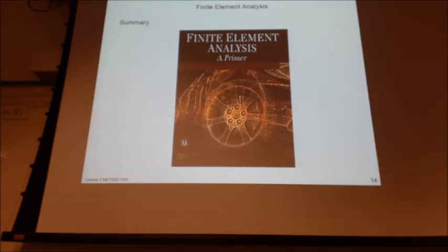So the qualification of assumptions is the key to a successful use of FEA, and you must understand the mechanics of the materials, the failure modes, the manufacturing and operating environments this device may encounter, and you must be able to understand the capabilities and limitations of the element type, whether it's a truss or a beam or a shell, that you are employing to conduct your analysis.